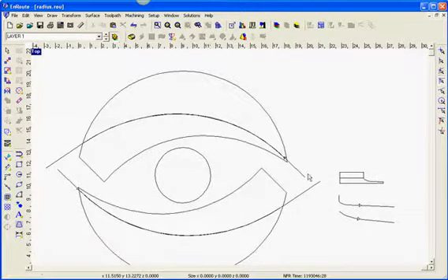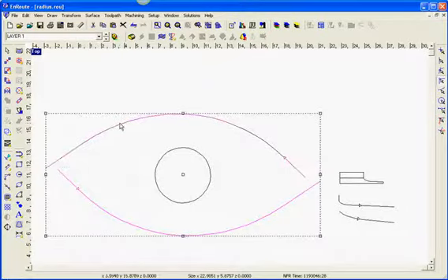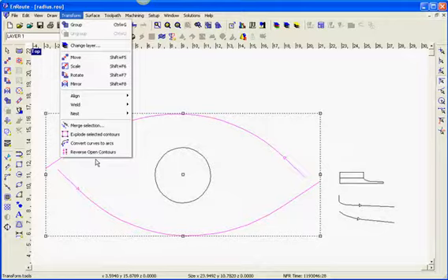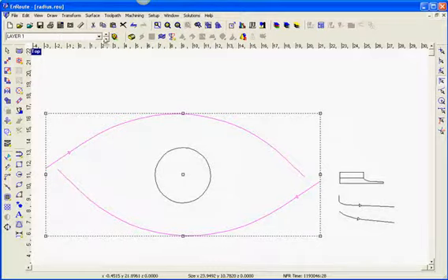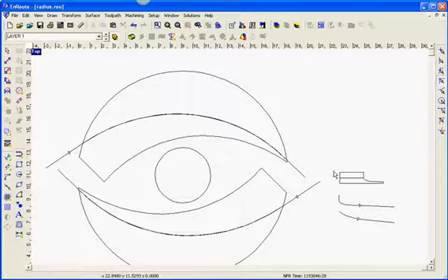If I turn everything on, now I want to start off here as my bigger part and go here, so I'm going to take this. I can see because of my arrow here that I'm going in the opposite direction. So I'm going to select each of these and go to transform, reverse open contour. That way when I'm extruding, I get a better idea where I'm extruding at on the part here.